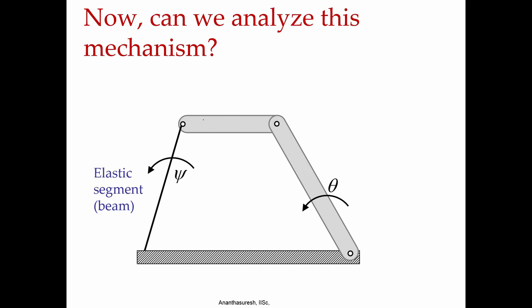Can we do this? Can we analyze this? So, if we say that there is some torque over here, can we analyze it, meaning can we see how this deforms, how the coupler link deforms and so forth. The answer is yes, because this is fixed here and it is movement free over there, and load can come in any direction. We know how to deal with that. We can replace this with a pseudo rigid body model where the length is shorter, put the beam there, put a torsion spring, and we can analyze it.